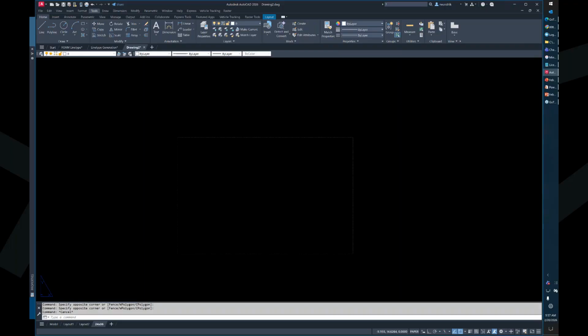I make a block of all my P and ID line types. I put that block in a palette, and all I need to do is drag the block into the drawing, and boom, all the line types are there. That works too. There's nothing wrong with that. I just like to be a little more surgical, because I don't like to have a lot of things hanging out in my drawing that I don't need. Unless you explode that block, you can't purge any of those extra line types. But it does make sense if you constantly are using those.